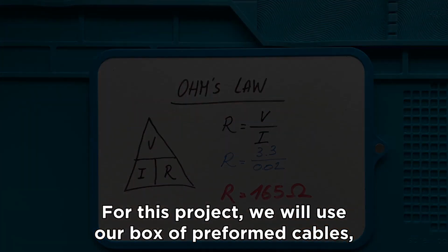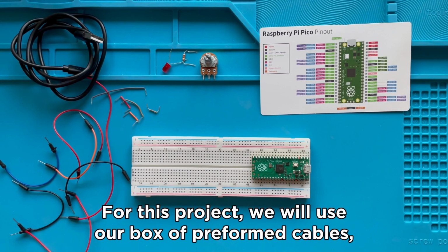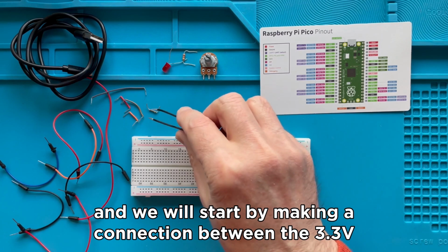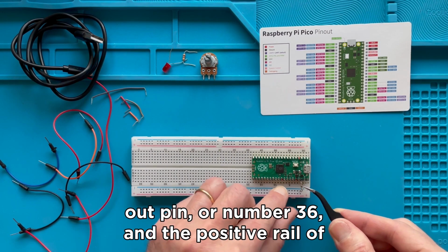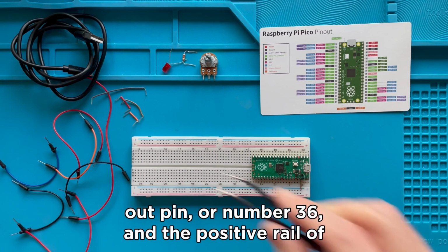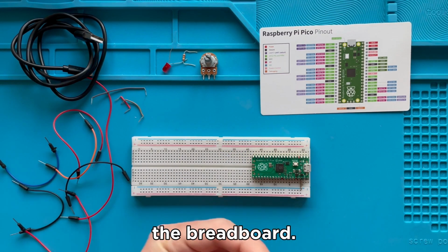For this project we will use our box of preformed cables, and we will start by making a connection between the 3.3 volt out pin, or number 36, and the positive rail of the breadboard.